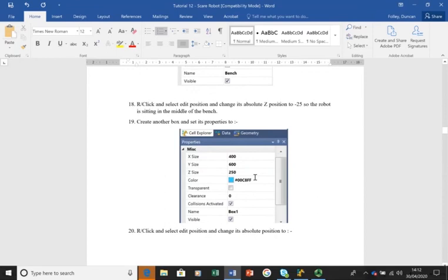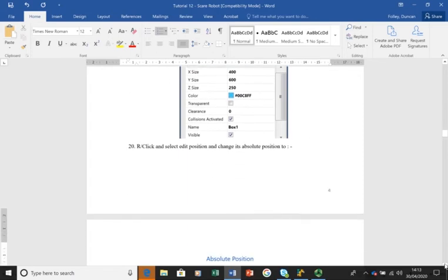The Stäubli software is not a 3D modeling package. We can do some really, really basic stuff, but that's about it, and it even struggles with that. So if you need some really complex 3D modeling done, use something else. If you are going to do any 3D modeling and bring it into the Stäubli, think about how much detail you need in that model, because it will slow the Stäubli software down terribly.